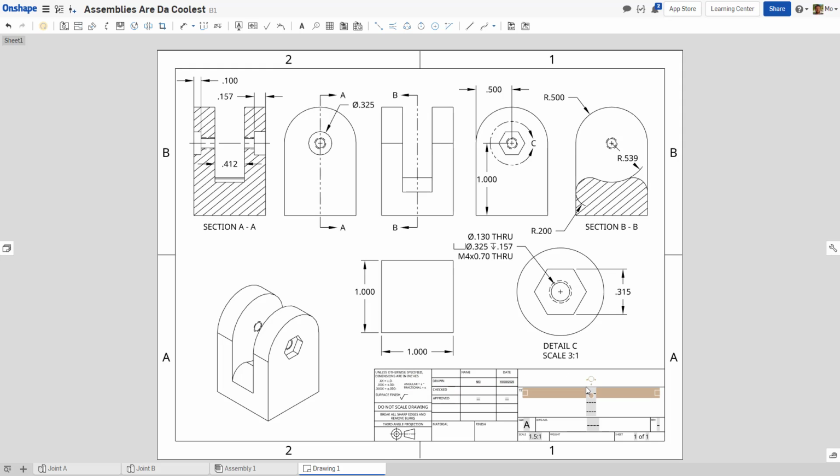If I hover over these cells, you'll notice that an alternate text appears, stating that this is a sheet reference to Title 1. Similarly, on other fields, we get sheet references to Title II and other things like drawing part number. Rather than editing these items directly, we can edit the metadata that is part of the document properties of both the sheet and the parts that this drawing are made of.